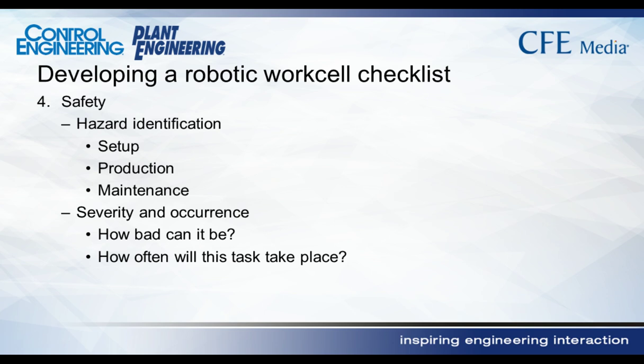So you're not just thinking about safety while the cell's running, but if I have to enter the cell, do I have to stand on top of something in order to set up a part? How can I mitigate that risk? There's production things to think about.